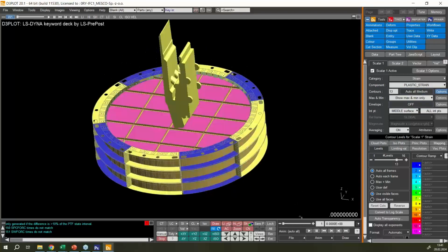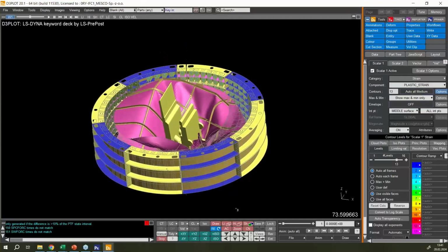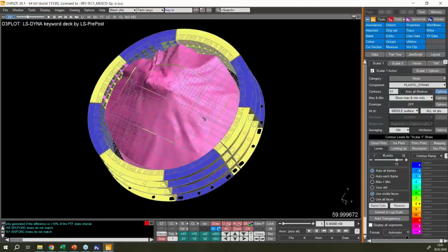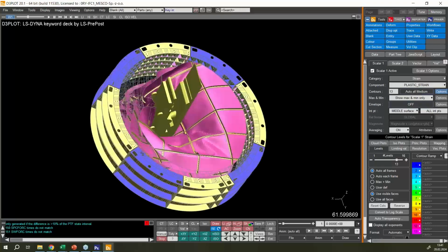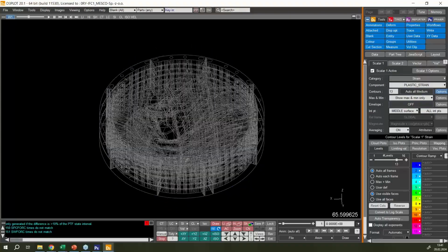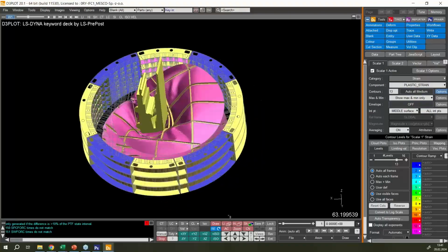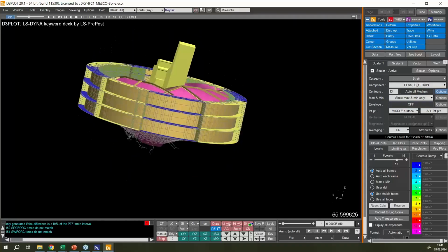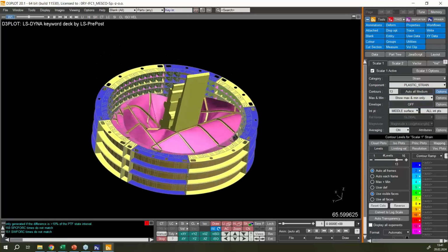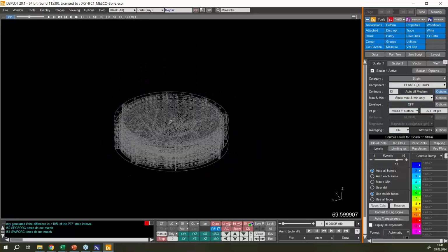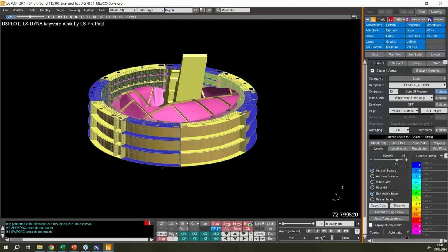Let me just position that right and play the animation. As you can see, the animation is smooth even for that large model. We can see some beams breaking. Those are the steel ropes that are catching the debris, and the debris right there weighs 20 tons. So it's a pretty heavy piece of equipment, and we can see that our structure is catching and dissipating the energy of that equipment. The height of the drop is about 1 kilometer. So it's a pretty fast moving object to catch.